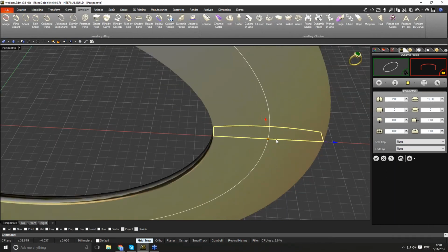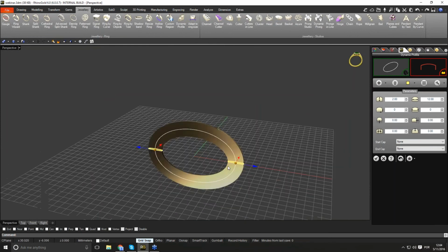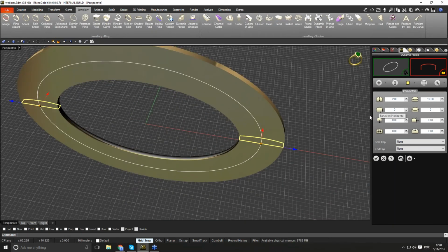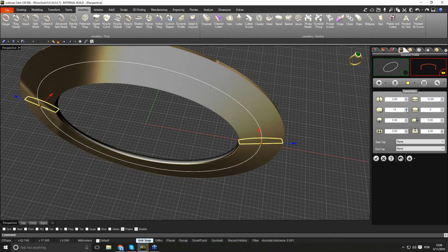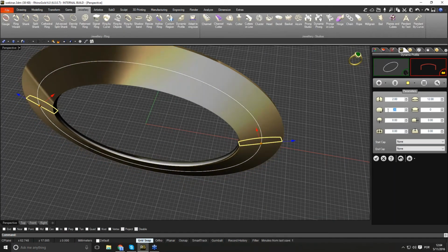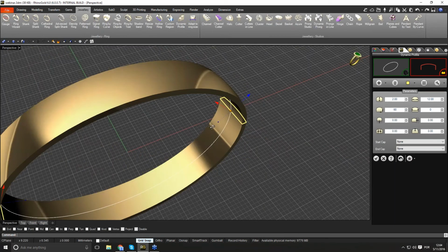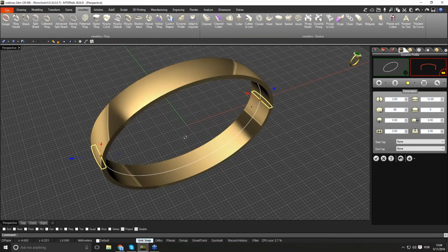The last step I need to define is the angle. This is not the position I want, I just need to rotate. You will see in here that I have the horizontal rotation option. So I just need to start defining the rotation angle. In this case, I can see that it will be minus 90 degrees. And from here we have the model exactly as I want.